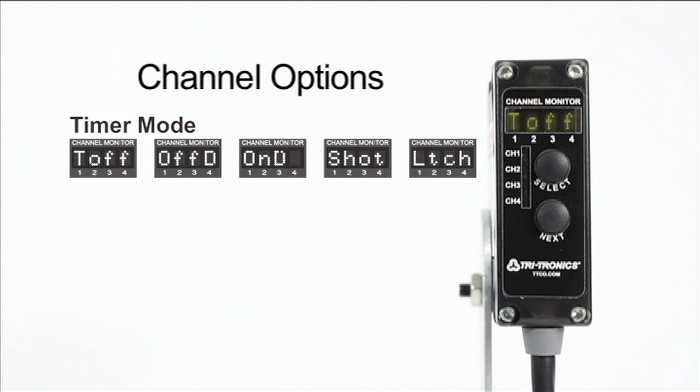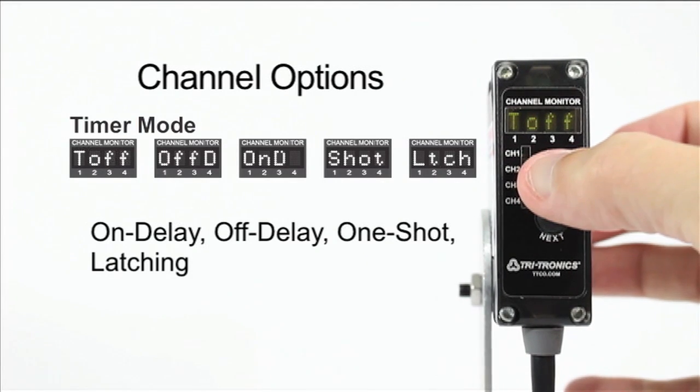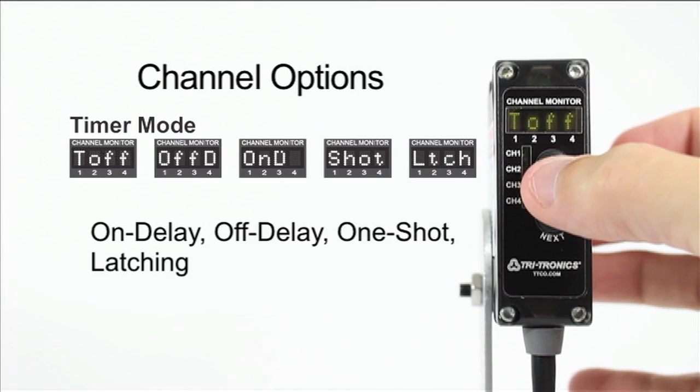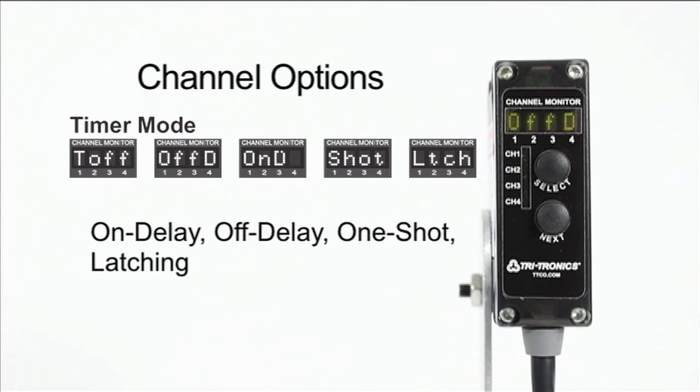Timer mode allows you to add an on delay, off delay, one shot, or latching to each channel. Press Select to step through the timer settings. Timers can be very helpful in handling a variety of applications. Timer off is the default setting for this option.